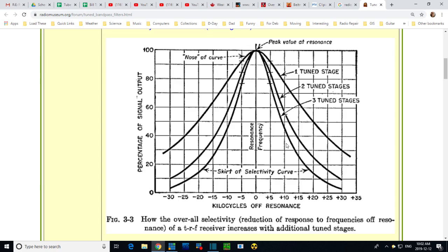The image is like a signal that cheats its way into the radio through a, what would you call it, a back door, if you like. And that's happening way out here at almost a megahertz away, not 35 kilohertz, almost a megahertz away, because it's double the IF. So, if we pretend this signal is 600 again, as we've been experimenting with, then the local oscillator is out here at, was it 1055? So where would that be? So this would be 600, 605, 610, 620, 630.